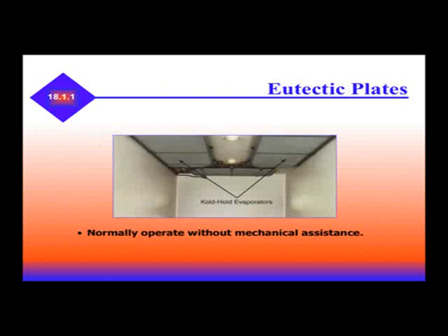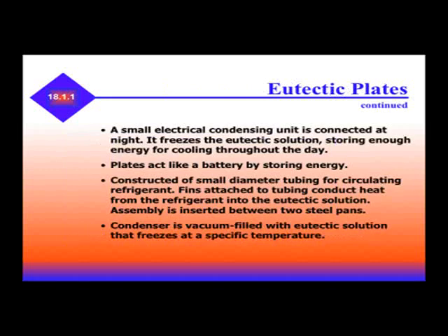The eutectic plates normally operate without mechanical assistance. A small electric condensing unit is connected at night. It freezes the eutectic solution, storing enough energy for cooling throughout the day. The plates act like a battery by storing energy.